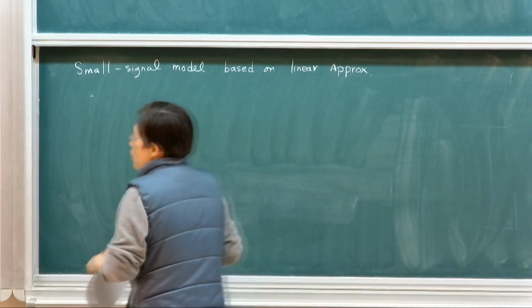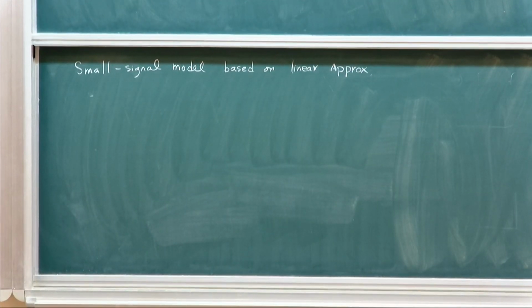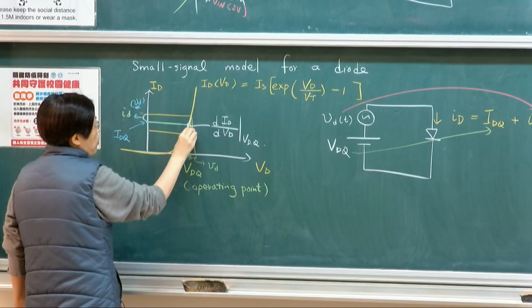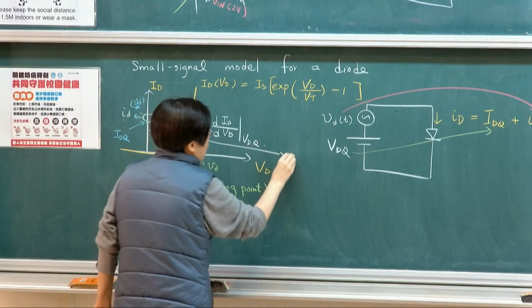Based on something called linear approximation. If I'm only moving not far away from this operating point, a simple way of projecting what happened is to find out di. So what I can do is find the slope at this particular point, di/dv, if I'm projecting this using a linear model. I'm just going to get the slope